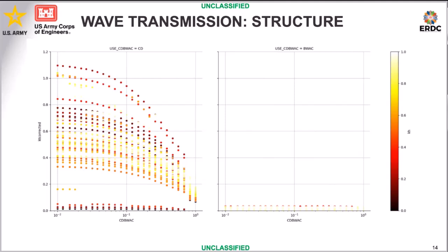And of course, this parameter space for transmission is just one snapshot of a very specific freeboard, width of the structure, and slope of the structure. So in theory, as we continue building this matrix, we can hopefully provide design guidance for different geometries of standard trapezoidal breakwaters, and provide some recommendations as to what kind of wave transmission you might see from those breakwaters.